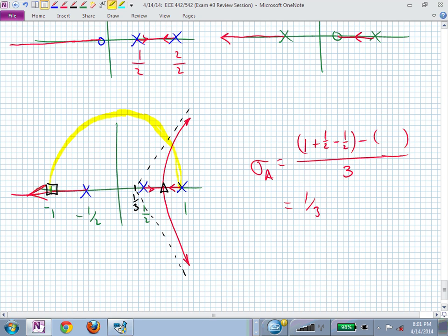It can't be greater than 2, but it probably is even going to be less than 2, isn't it? Because when you hit a gain k of 2 at the square, you may already have zipped out. Those complex roots or branches may have already escaped the unit circle. Is that clear? And you don't know from that limited piece of information. You would have to compute the values for the gain to get you there.